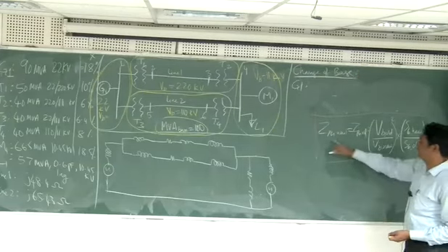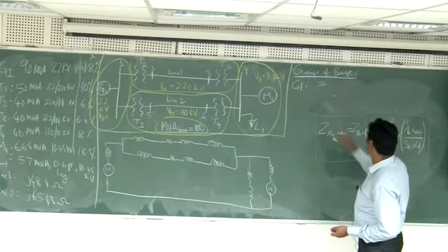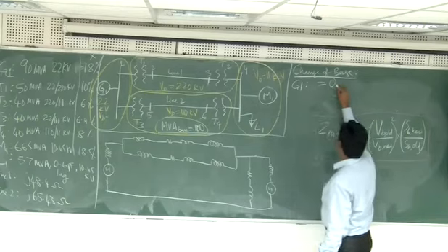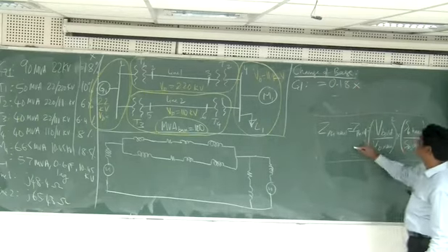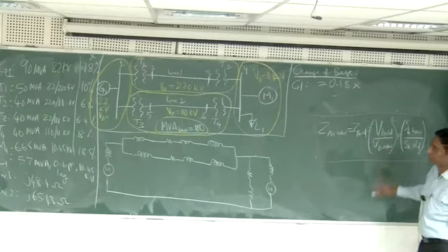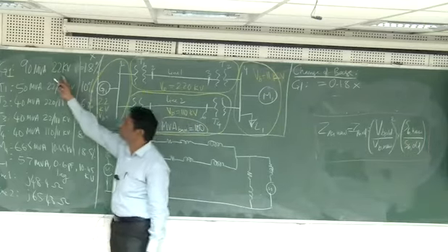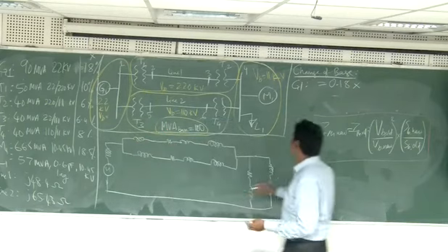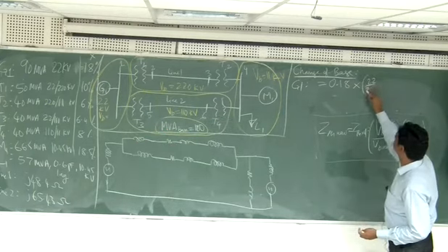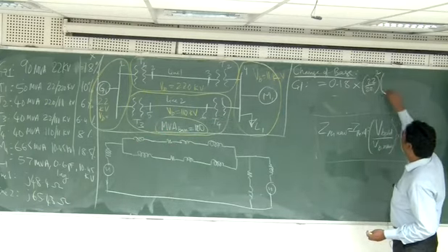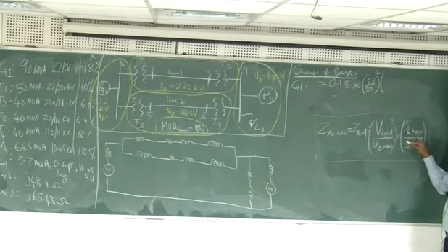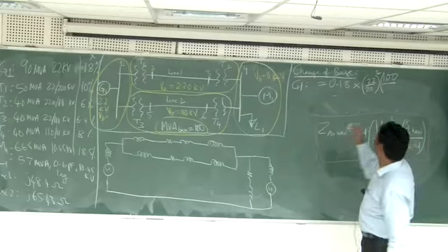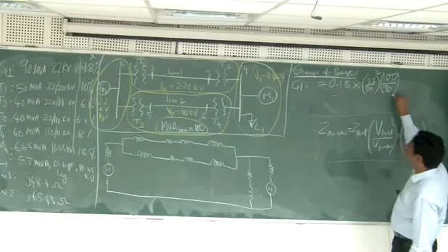So this one I want. What was the old one? Look at 0.18 multiplied by what is the old voltage and what is the new voltage. The 22 kV what the manufacturer has used, 22 kV what we are using. So I'll just put 22 by 22 squared, and then what was the S? It is 100 MVA, and what was the S base? It is 90 MVA. If you do this calculation, you will get some number.